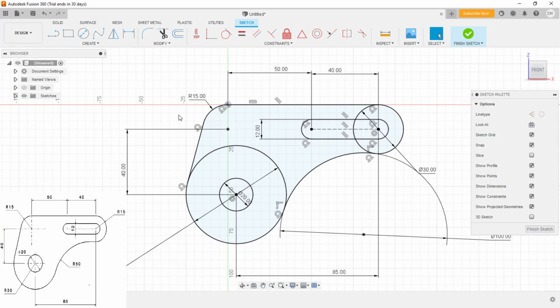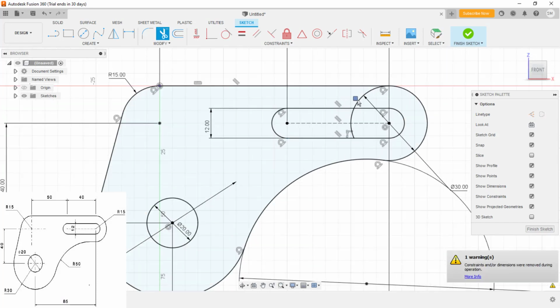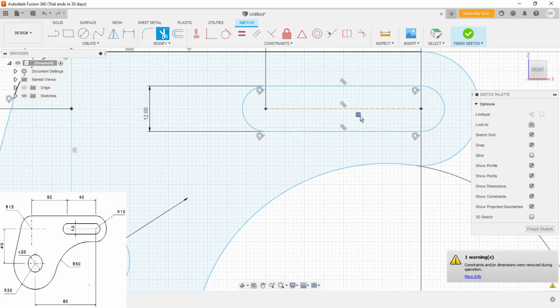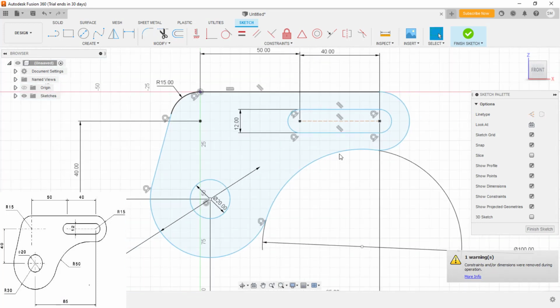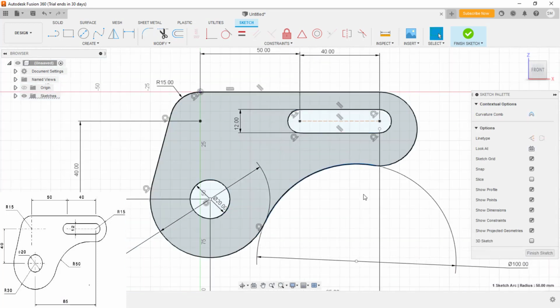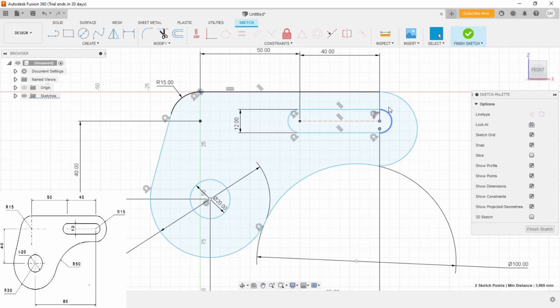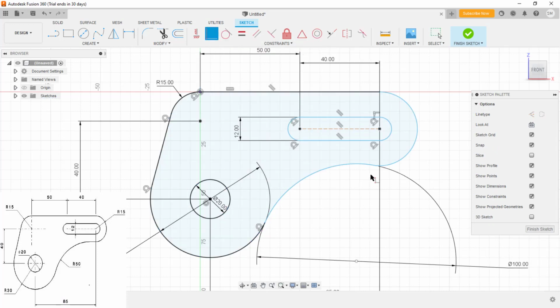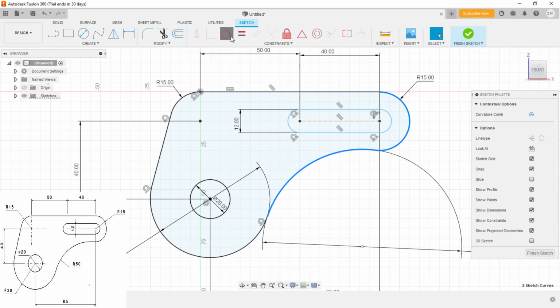Yep. So now we can trim unwanted edges which are not needed, and actually T is a shortcut, remove these, but still undefined. Yeah, tangents are missing, these two should be coincident, the point is outside. The radius I need to define again, 15.